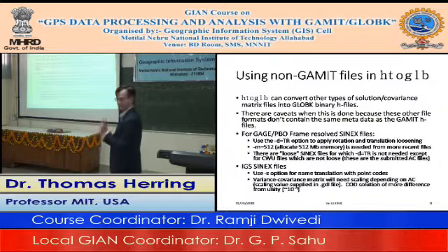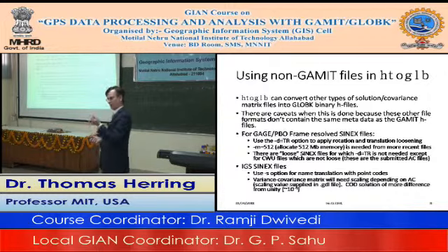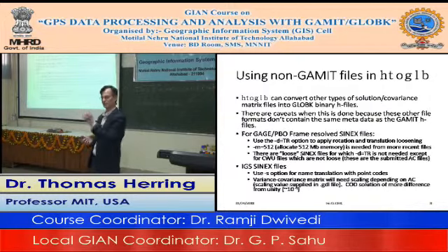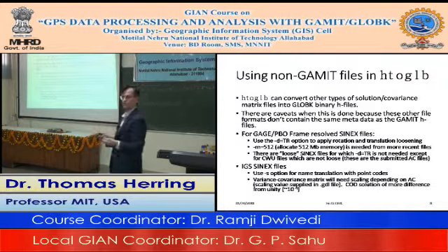There's a caveat in that many of these file types do not have the same level of bookkeeping that we have in GAMIT. We copy through into our files information about the ocean loading you used, what sort of atmosphere models you used, the tide model you used, and that is kept intact in the files. These other file formats often don't have that information, so we can't carry it through. So be a bit careful about the metadata that's actually in there.